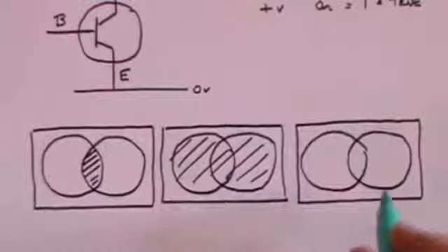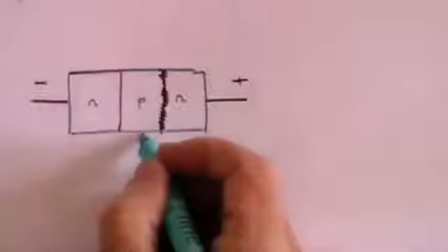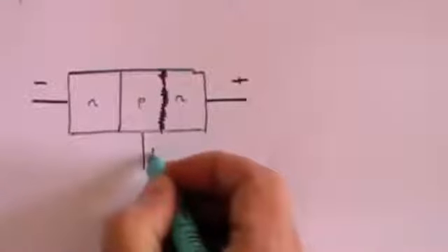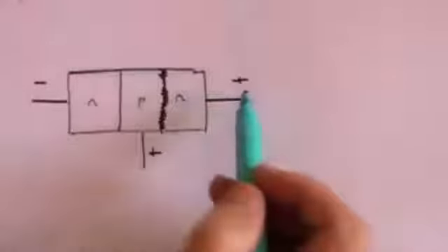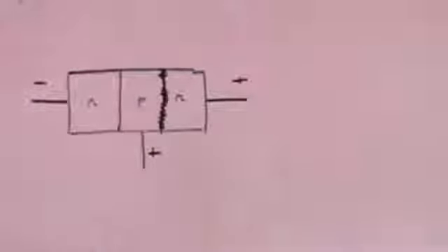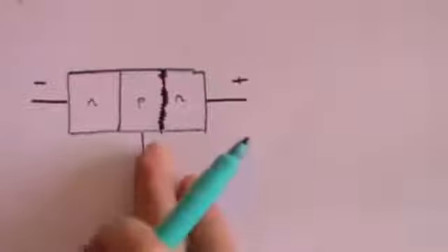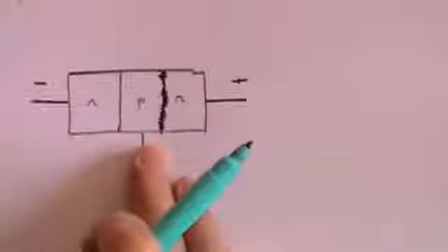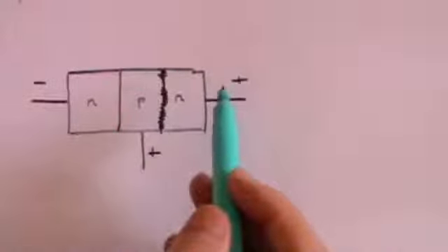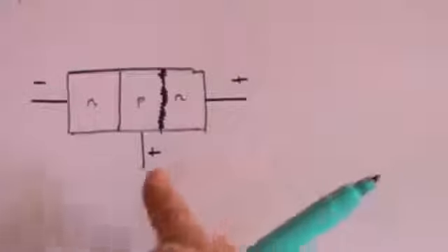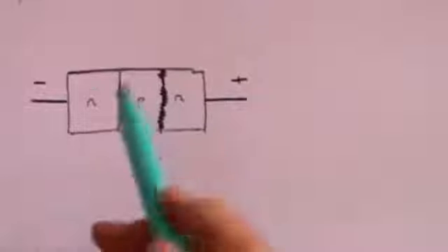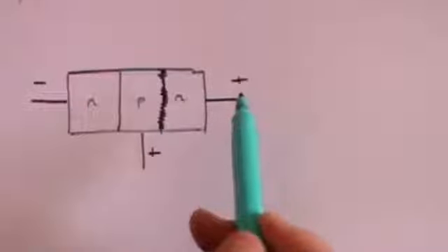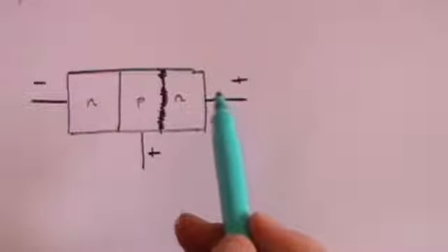Electrons from flowing. But if you put a positive charge at that point, then the electrons will indeed flow across. And so this is essentially a switch. If there is no positive charge at that point, no electrons flow. In other words, no current flows. But if you put a positive voltage at this point, then the electrons will flow and a current will flow.